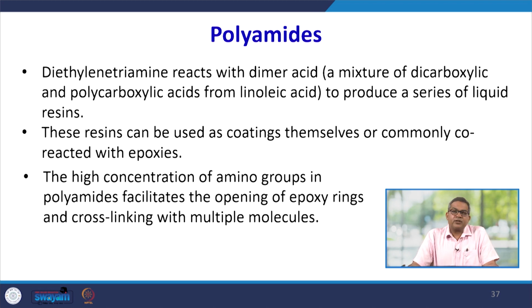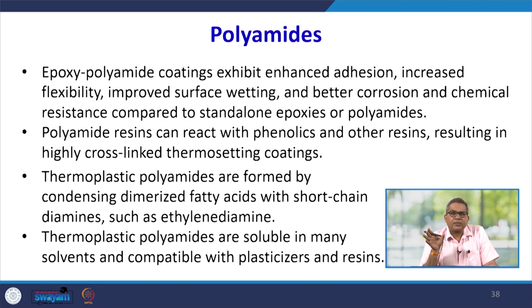The high concentration of amino groups in polyamide facilitates the opening of the epoxy ring and cross-linking with multiple molecules. Epoxy polyamide coatings exhibit enhanced adhesion and increased flexibility, improved surface wetting, and better corrosion and chemical resistance compared to standalone epoxies or polyamides.